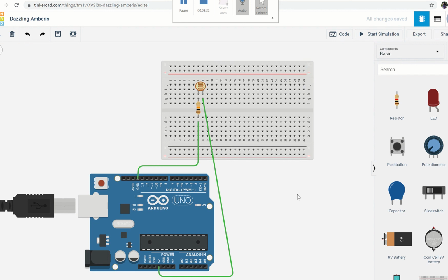So this is our circuit, but remember, we're going to have an analog input between this photoresistor and resistor, so it's anywhere along this row 7, right? I'm going to start on here, in between them, and we're going to go to the analog pins, which are at the bottom, so I can go around here. So that's our analog 2. That's our circuit.